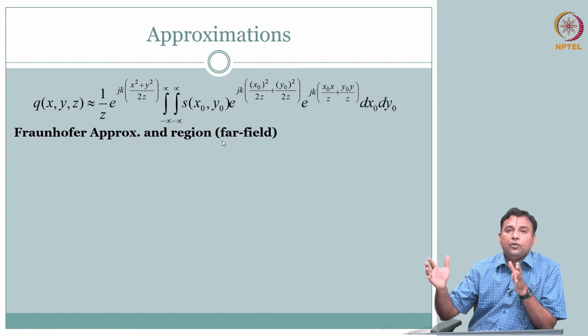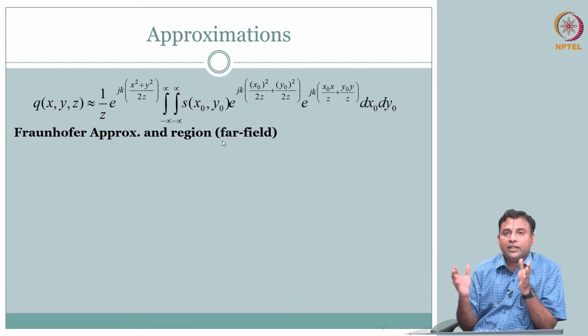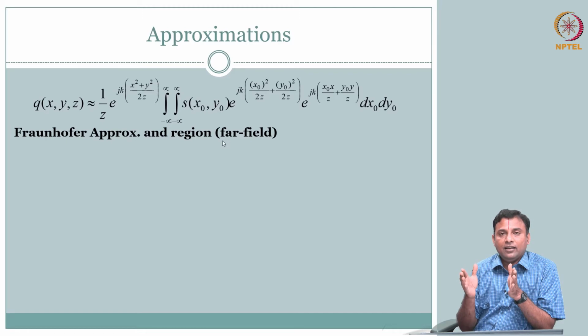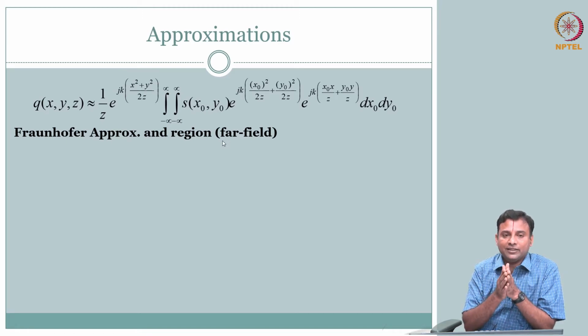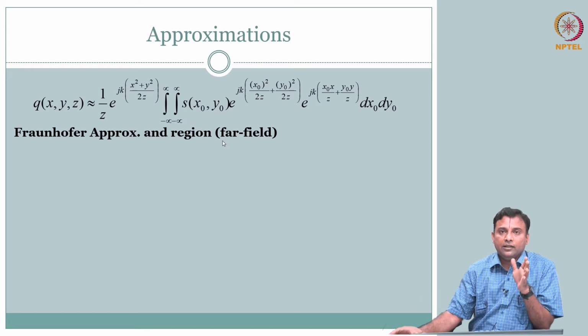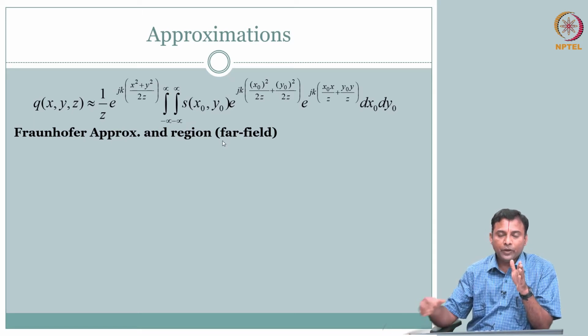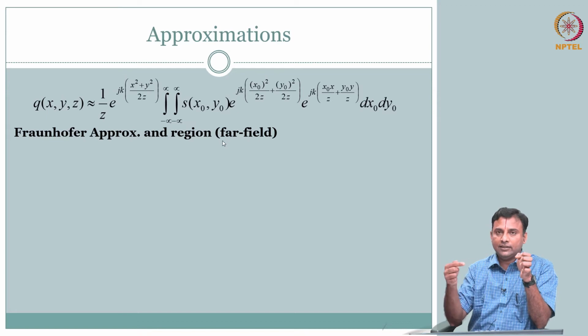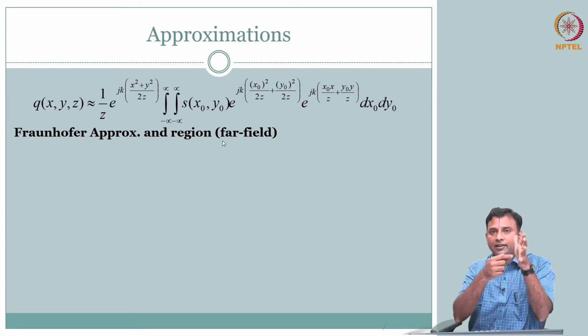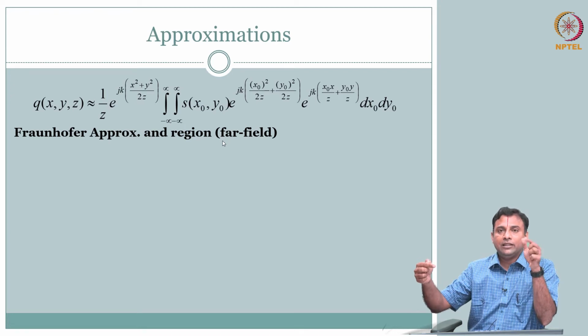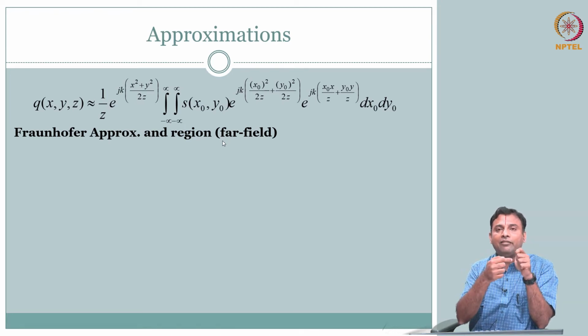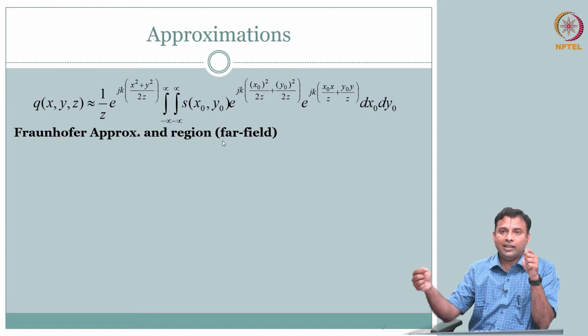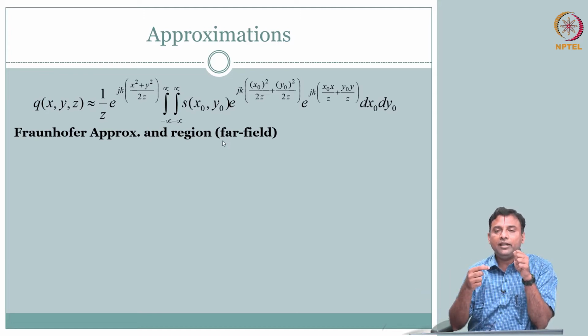How far are you? So we should have some condition under which we should say you are far. All this in relation to where your transducer face is, right? So when you say transducer face, you can clearly, intuitively guess the influence of this face is going to be the distance. If I have a bigger face, I will probably have its influence in a farther region. If this is a smaller face, probably I will have the influence over a smaller region. So this near or far, you can intuitively guess, is going to be in relation to the size we are talking about.